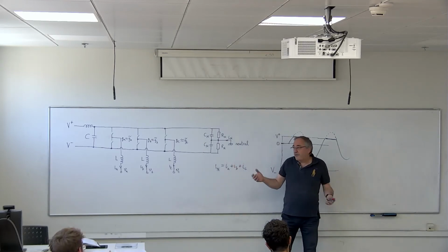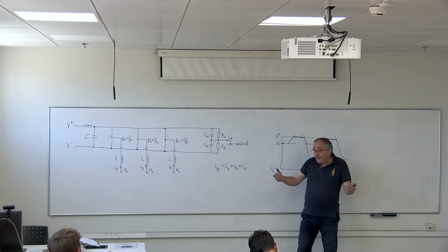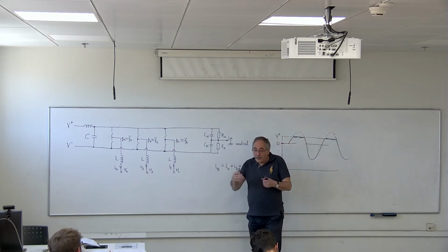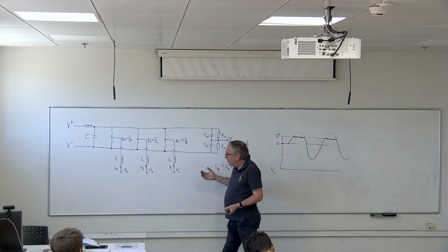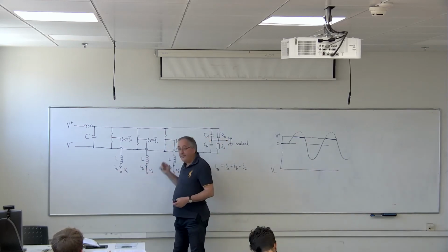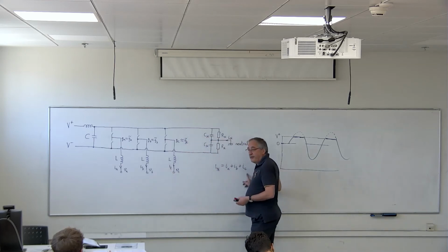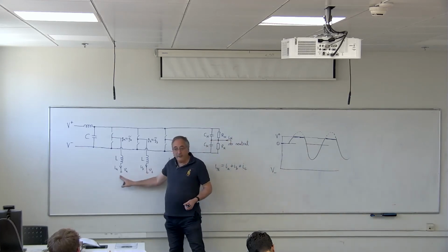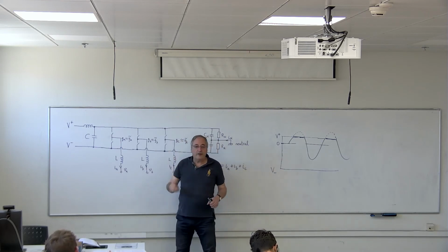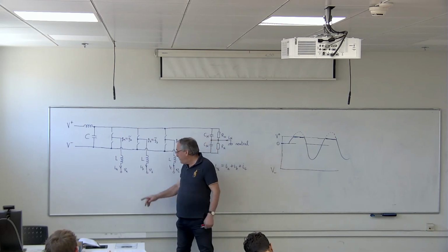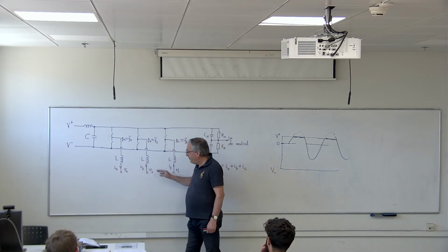Let's say that suddenly some consumer, even an air conditioner, it's still one phase, starts operating, and it's connected to one phase. That means that suddenly you have an additional 2 kilowatt on one of the phases. Now, this means that the phases are not balanced. The sum is not 0. Let's say it was balanced up to that moment, and then suddenly a one phase 2 kilowatt air conditioner connects to phase A. Then there will be suddenly 2 kilowatt flowing through phase A, and all the rest has been balanced.